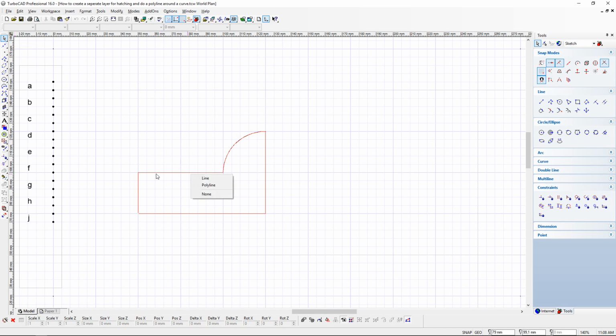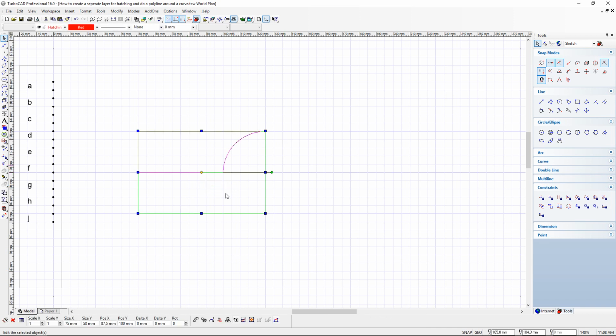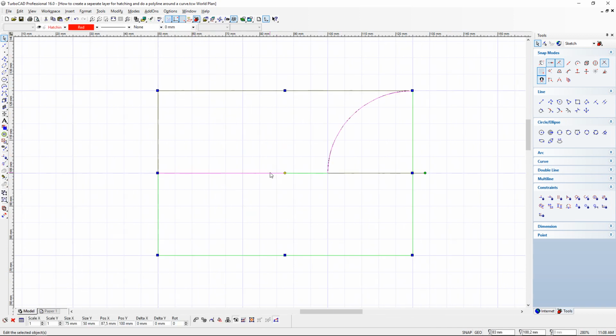Now if I click on that line or any one of these lines, this will pop up. It will allow me to either select the individual line that I used on my answers layer, which created my model, individual lines one at a time, or I can select the polyline, which will select that whole polyline and its surface. So I'm going to select that, and then this window opens, or the selection happens, and then you'll see there's this yellow button in the middle.